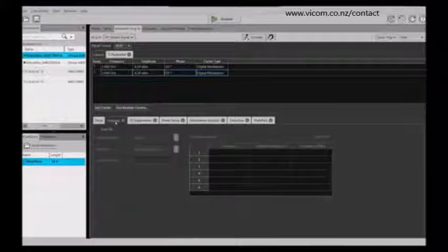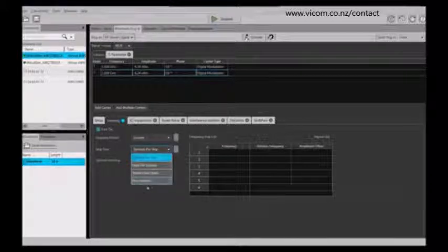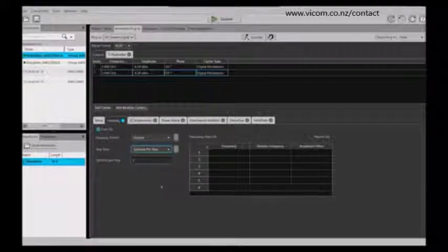You can then go in and have the capability of turning on hopping, such that you can hop from one frequency to another. So you can specify quite a few variables within this hopping characteristic. So you can symbol hop. You can specify your hop duration, your hops per second, basically all the characteristics that you need for your hopping, how many symbols per hop, and then you can use, if you have a particular custom pattern, or you can use a pseudo random list or a range of hopping frequencies that you want. So this gives you a lot of flexibility.